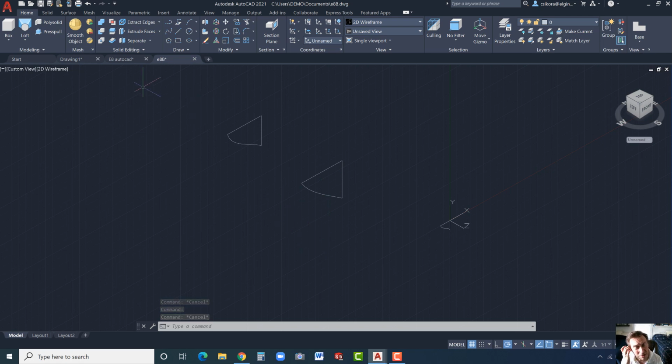All right, and a spline, by the way, is a freeform geometry. Initially, splines were based off of polynomial splines, which some of you might remember from math class in high school, even when you dealt with polynomials. Those have transitioned over the years, especially around World War II, the development of curves for aviation and then the auto industry. And so you ended up going to what they call curvature continuity, and what they have now is G2, G3, and G4. And there's also T-splines, which I don't think are in here. This can handle, though, NURBs, which are non-uniform rational B-splines and things like that.